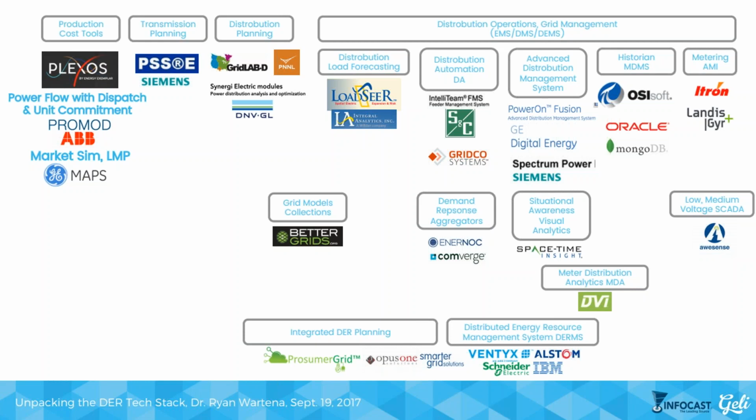But the low voltage and medium voltage SCADA hasn't had the strong support to have mass rollouts. So we can see now for DERs to actually be integrated into the system, we need to know what's going on on the lower sides of the system. That's been one of our learnings here at Jelly: there need to be other approaches if a utility doesn't have locational awareness of what's happening on the low voltage and medium voltage system, and maybe only at the substation.